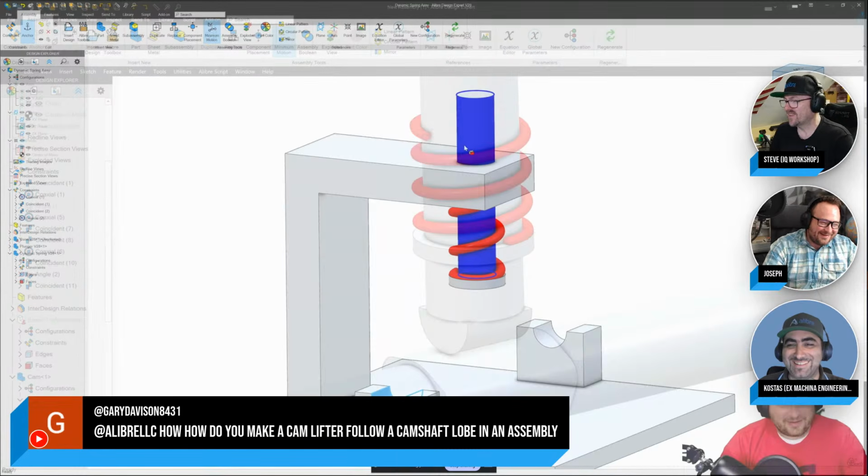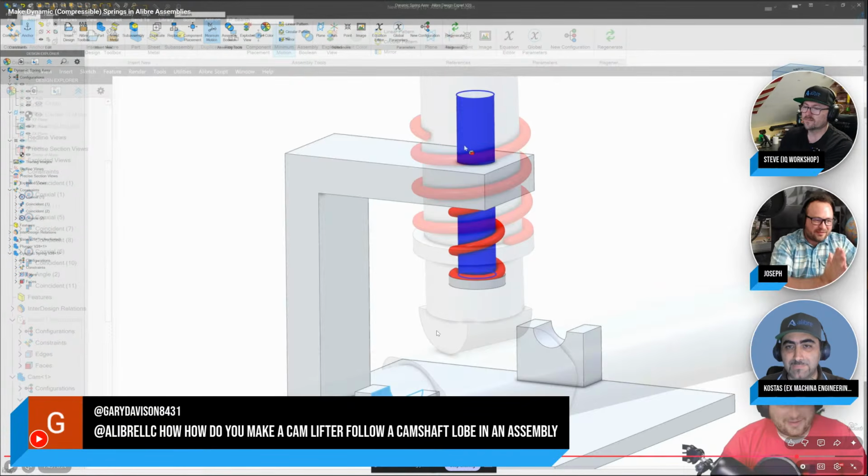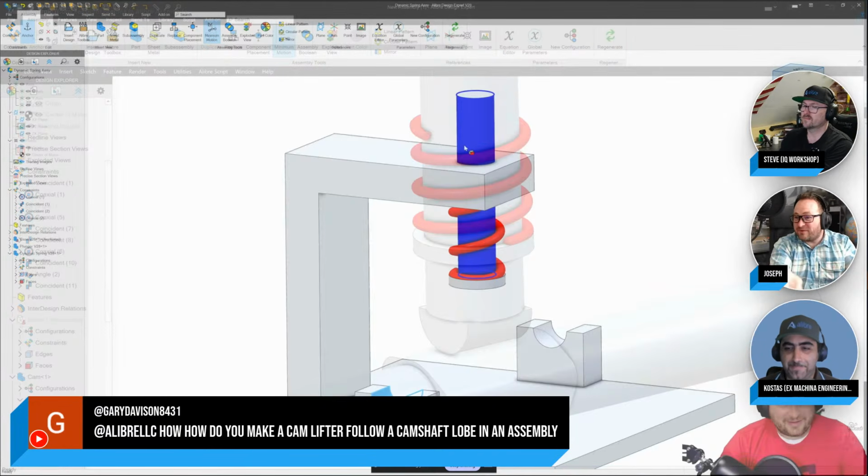I get it. Basically what we do is a design in context. So we have this cam lifter, and then we have this part that we make in the context of the assembly, and we say the sketch that defines this arc is tangent to this lifter. Now, this may actually apply to that S-shaped slot question too.